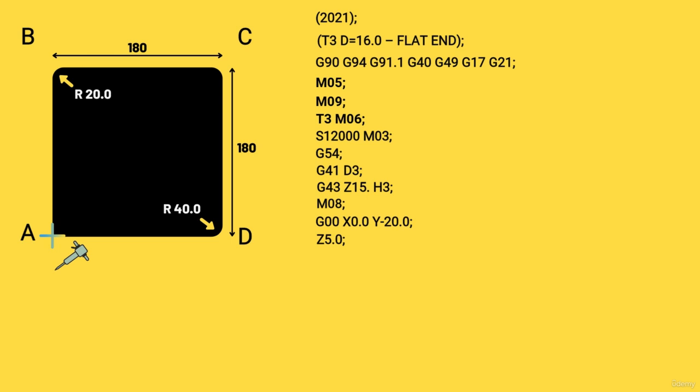Now as we move to cut around, our rapid travel command G00 is still at its tool change height, so we are going to rapid it down to 5 mm above the job. Now using G01 with a Z depth of -5 mm, we will take the cutter 5 mm deep into the material. Let's assume it's a 5 mm thick material, so this would take us right the way through the material.